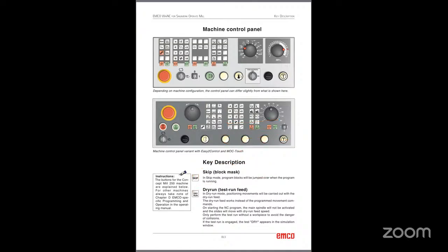So suppose you have a program, and say M30, M08. There is no need to execute this line. Just give a backslash like this. That means if the machine executes this line, it will skip it if the skip mode is on.